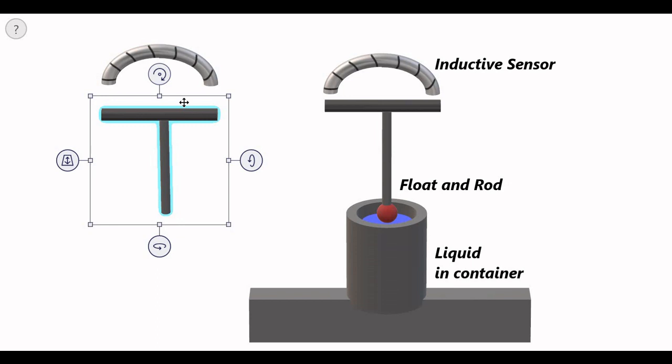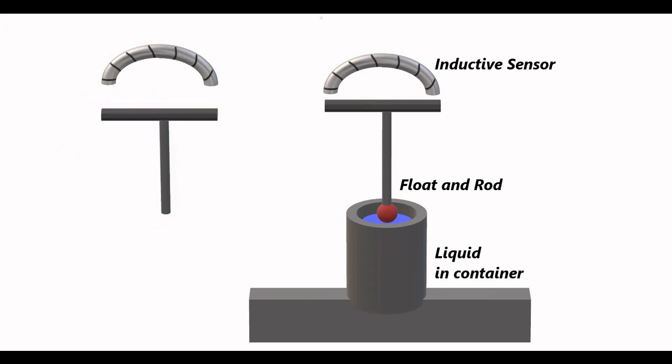So here we have used Bourdon tube for pressure measurement and inductive sensor for level measurement. So once we have got the parameters, that is the level H and the liquid column pressure, we can easily determine the density by this.